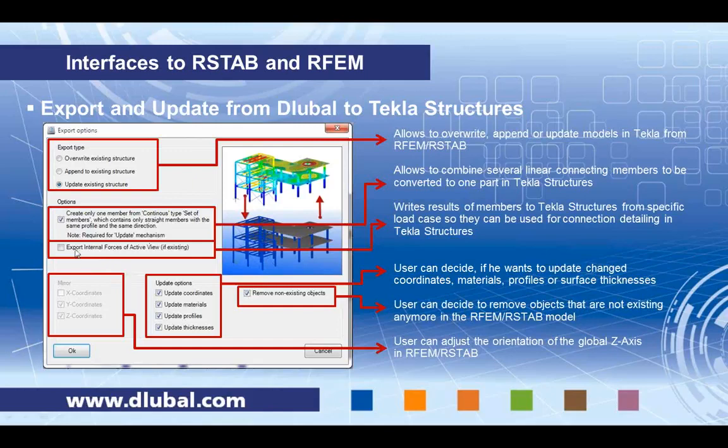I can also update the Tekla model with additional information like internal forces, and these internal forces can then be used inside Tekla Structures to have a better idea of what type of connection and which type of bolts and thickness of plates I might have to use.